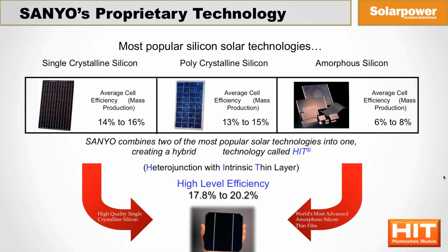So crystalline normally has a coefficient in the 46 to 50 range. Sanyo and some other more efficient panels, because it's not losing heat, because it's more efficient, they have a lower number. So that just means your system will produce more kilowatt hours when the weather is not perfect.